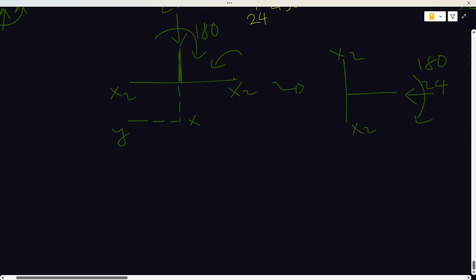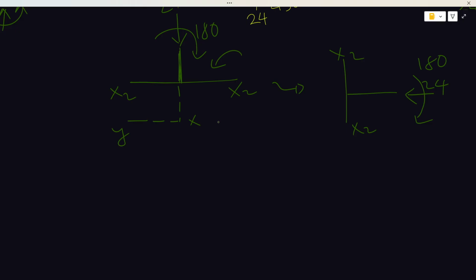So I'm sure that everybody is glad I showed them this. But okay, this is it. Now we can analyze. We can now say that Mx is equal to, now there's no moment that can come from any force here, just the moment coming from this couple, which is minus 180 based on our convention.